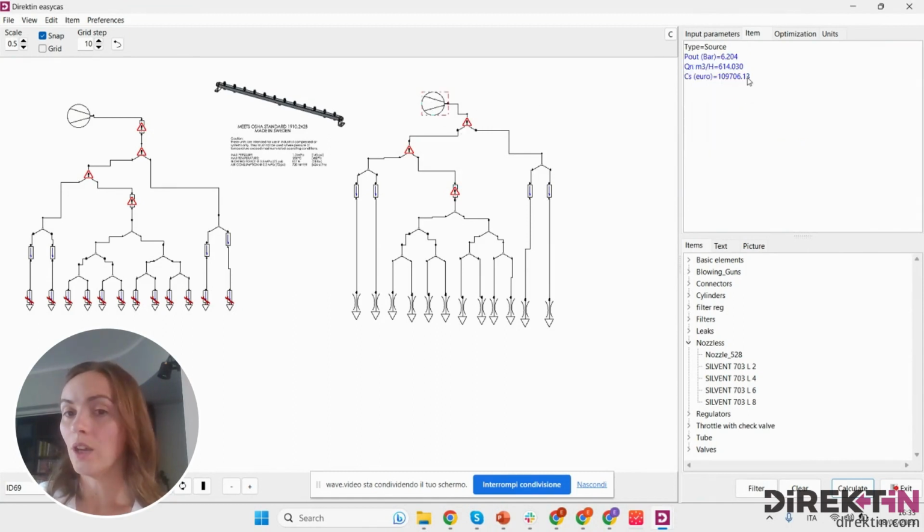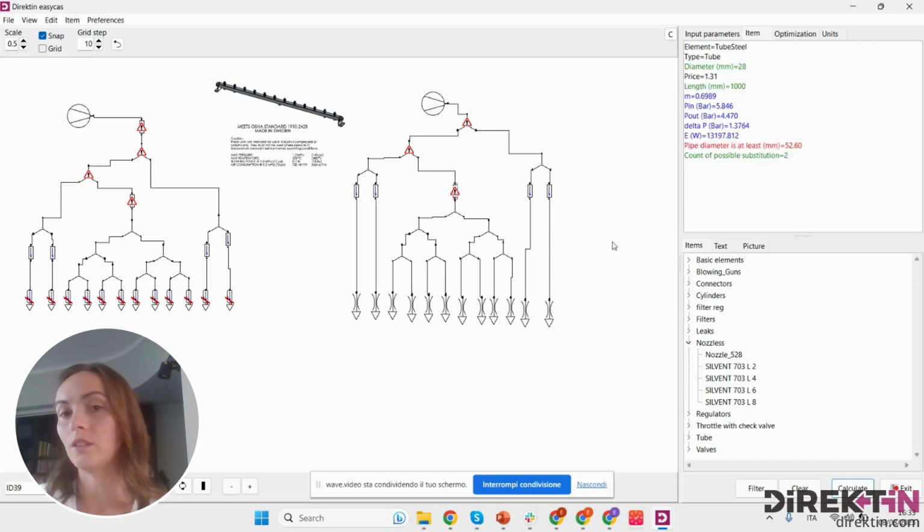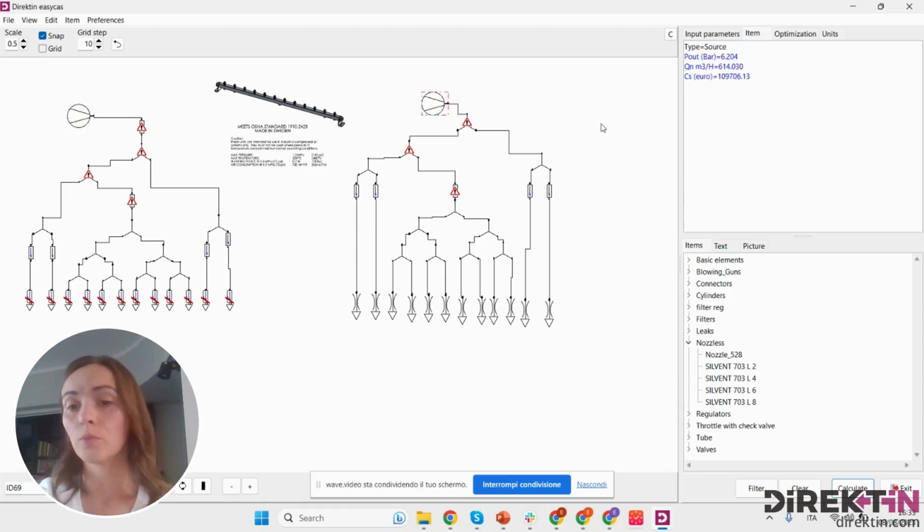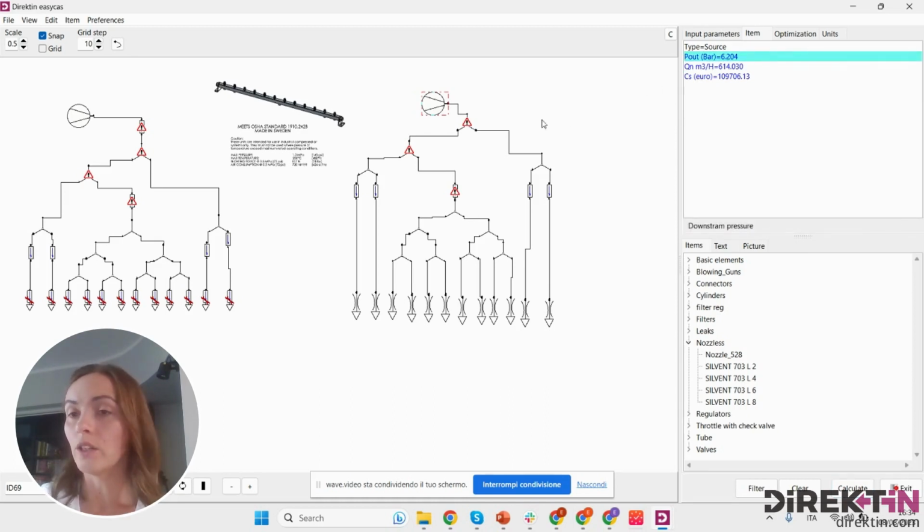And this would have resulted in a very high pressure drop, around 2.2 bars, as you can see there. If we model here for the 5 bar, as it was also planned and projected for the machine, the pressure drop will be around 3 bars. So this gives us already an understanding that the machine doesn't work and doesn't provide the pressure level of